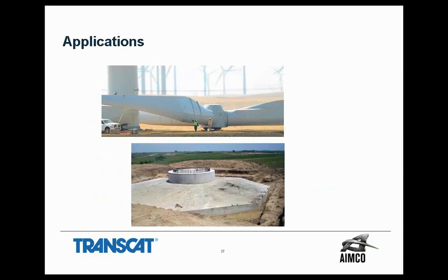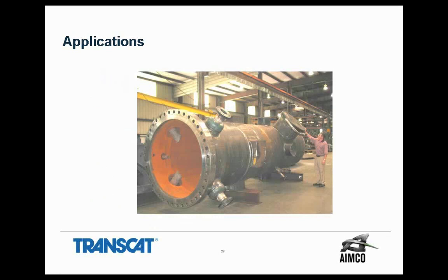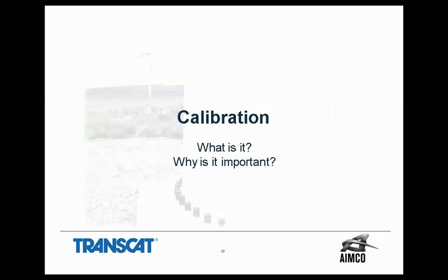As the applications we work with are large, very large, it's very important that we understand torque measurement, load, torque to clamp load ratios, all the variables that come into play, because we want these structures to stay in place and stay in service. And as you can see, these are very large flanges, very large structures, and it's critical that a torque connection is done properly, it's measured correctly, and it does the job that the design engineer expects it to do.